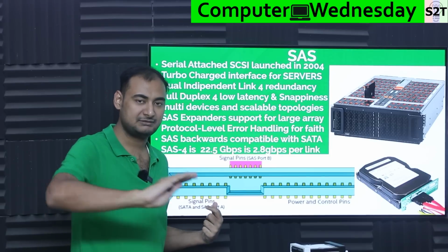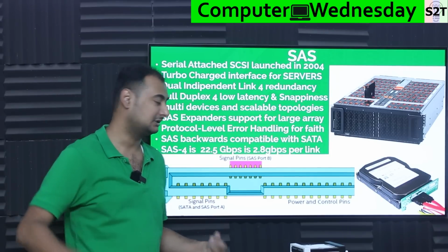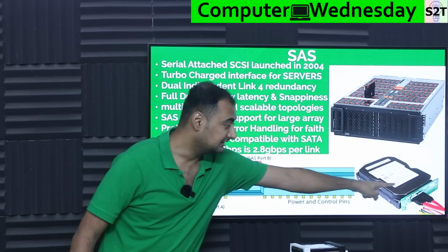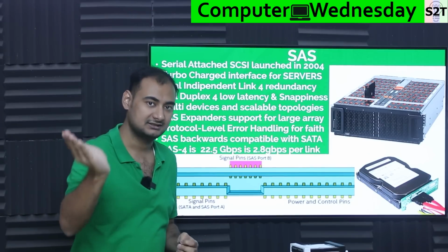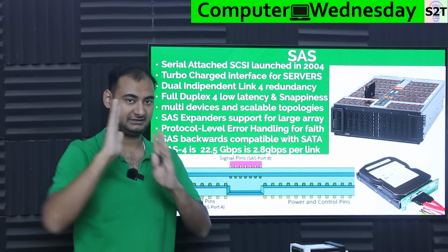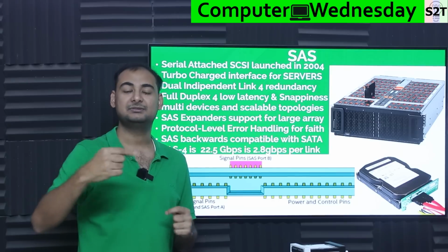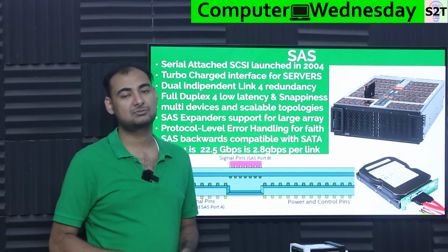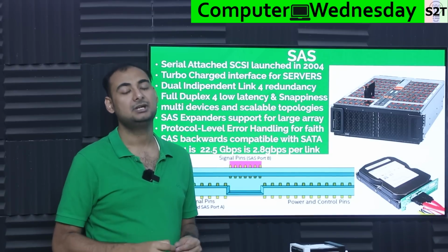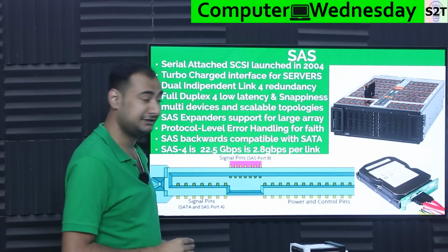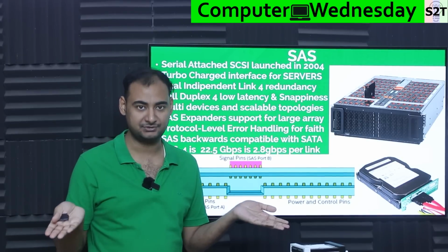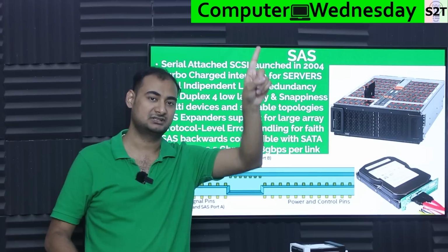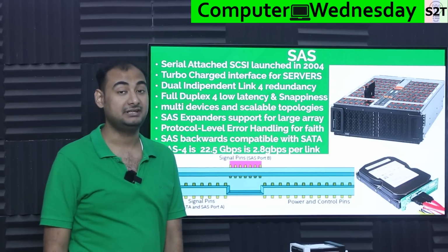SAS port A, all of them are wired through one way, going into one controller. And then there will be this signal pin B, port B, aka the other red wire that goes into the other side of the PCB, completely isolated, like there is a physical isolation, and it will go to a second host bus adapter. The likelihood of both host bus adapters poofing themselves is very low. And again, most of the time you will not even put them in the same computer. So you will have a JBOD, one will go to one head server, one will go to another head server. So that way you have very high uptime.